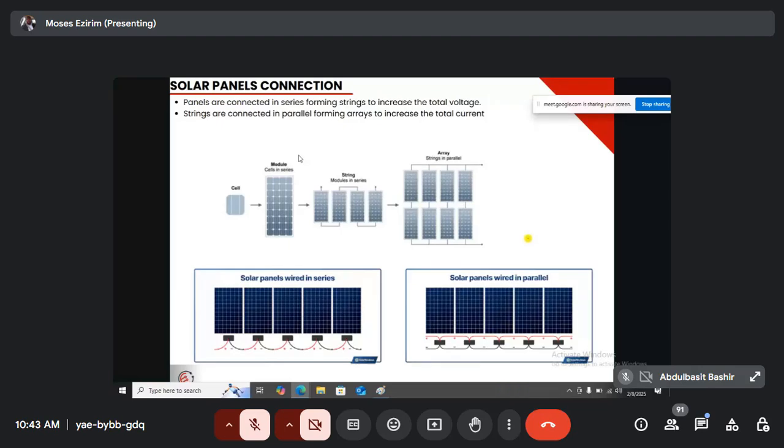What you will only be seeing is they will be telling you the voltage at maximum power, maybe 30 or 33 volts, depending on the type of the module. That is what you'll be seeing. So that means that if you are seeing 30.5, for example, now, that means that you need to arrange that 30.5 in series so that you can match up with that voltage of 300 to 500. I'm sure you understand what I'm saying.